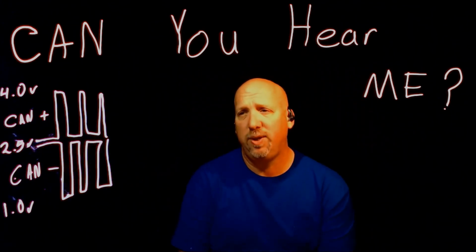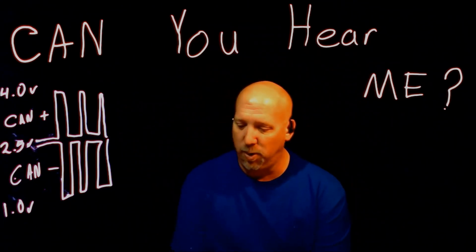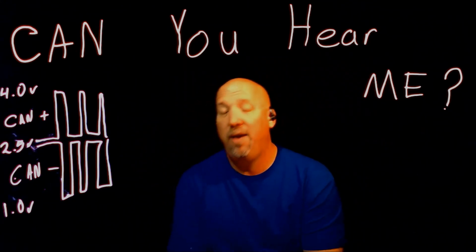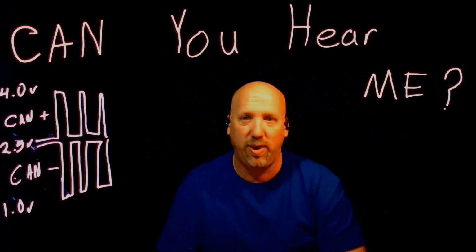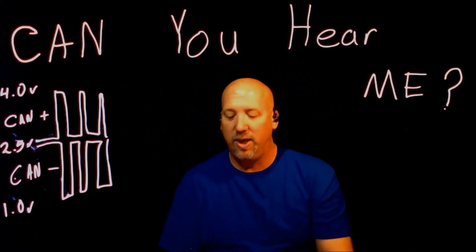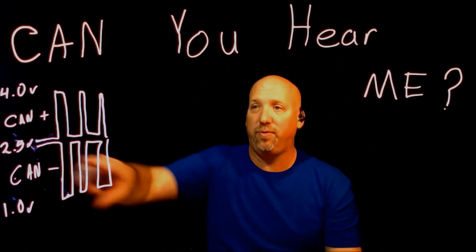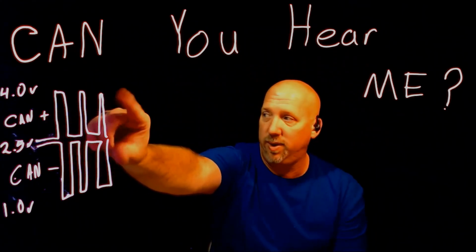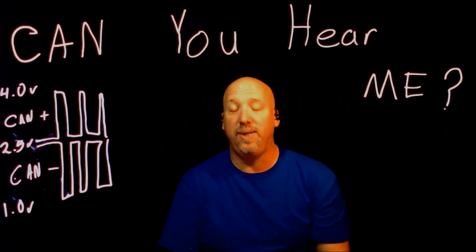So just be aware of that. If it is open, if that's your open, you can't have positive or negative. If there's a short between the two, somehow they get together. There's your short there. If twisted pairs have rubbed enough to where they've got a short, it'll prevent modules from achieving proper bus voltage differential, because remember that's a differential in voltage all the way through while it's communicating, in order to send a message.